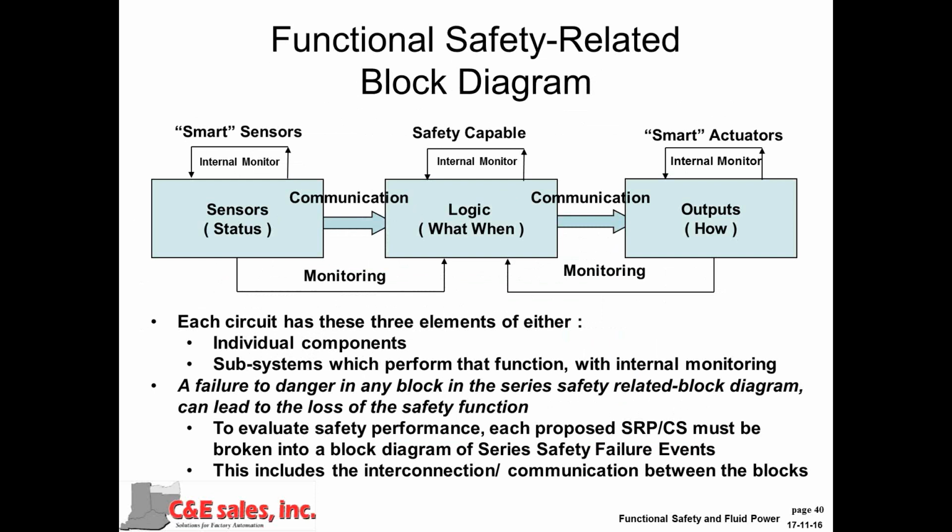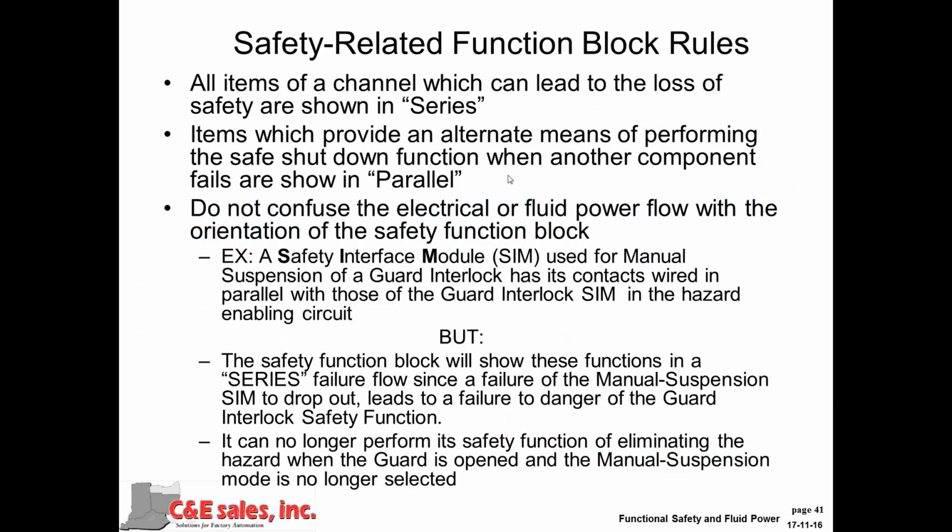Failure to danger of any one of these blocks results in the loss of the safety function of that particular channel. The question then becomes whether or not that means that the entire system has failed to danger. We'll talk about that in a little bit greater detail in a moment. Remember also the interconnection between these devices. Failure in those could also lead to the loss of the safety function.